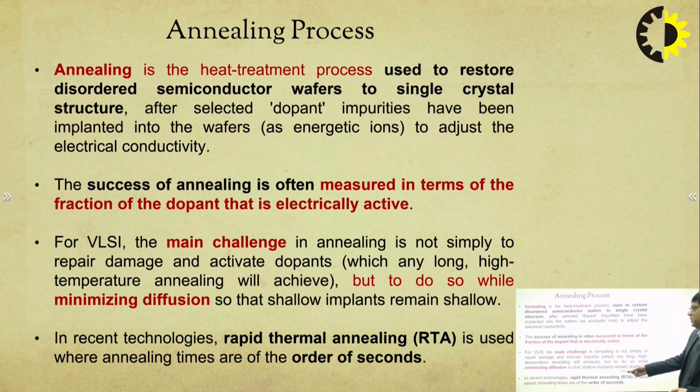So in annealing, the main challenge is not only to repair the damage and activate the dopants. In addition to it, there is one more important challenge, and that is that diffusion should not happen. We know that diffusion is a high temperature process, and annealing is a high temperature process, so when we are raising the temperature of the wafer, diffusion will automatically happen.